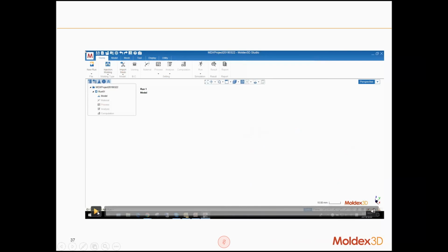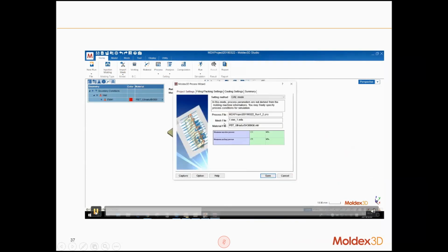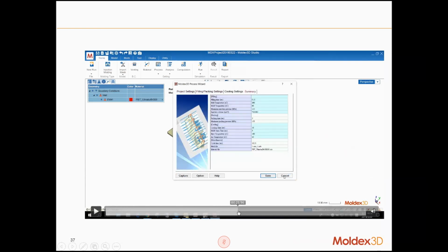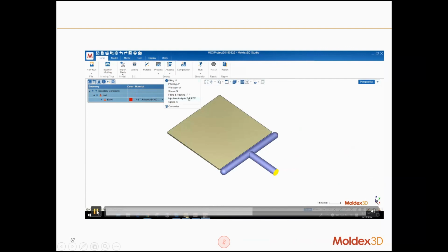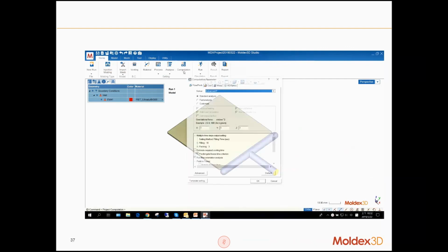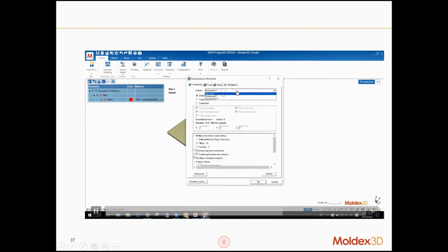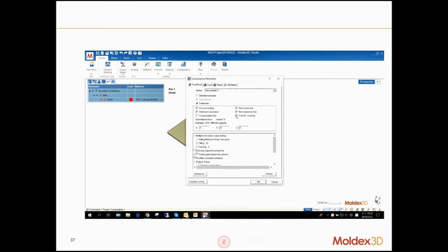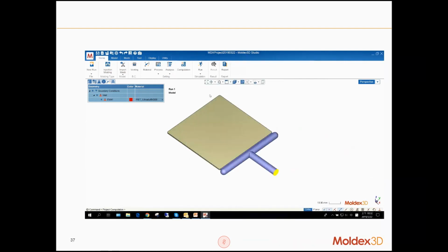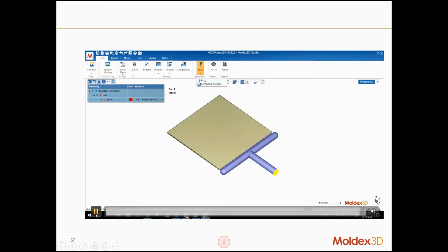Okay, to select the VE flow solver, first we need to have a project. I will speed up a little bit. In the computation parameter setting, we can select the viscoelastic flow. And we can decide if we want to couple the VE flow solver. And again, I recommend using the decoupled one for general cases. The calculation will be more stable.